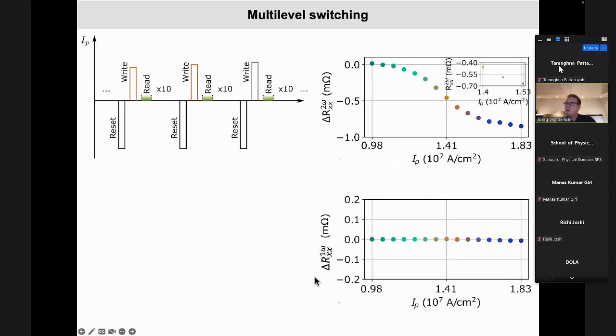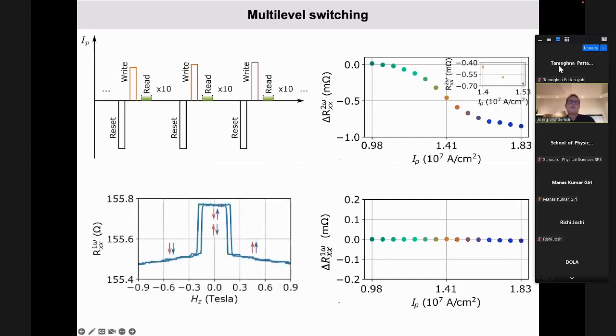Interestingly, our normal linear response, first harmonics, doesn't change at all. And this at a scale of our normal response, if we go from a parallel to anti-parallel state, which is 3 orders of magnitude more sensitive, right? So the first harmonics doesn't tell us anything about it, but the second harmonic tells us what state we are in and what intermediate state we are in. How is it possible to have those intermediate states?